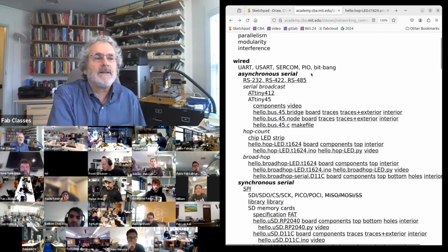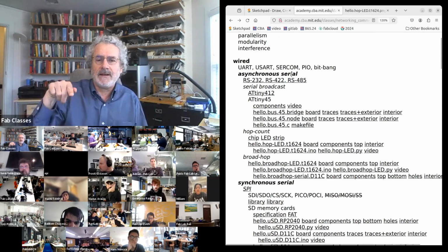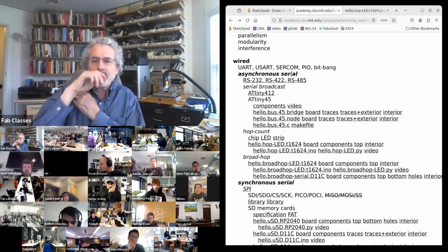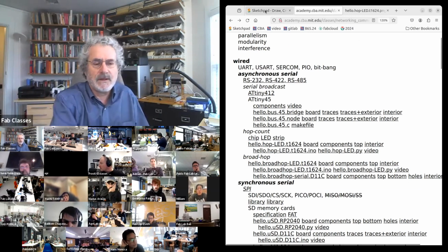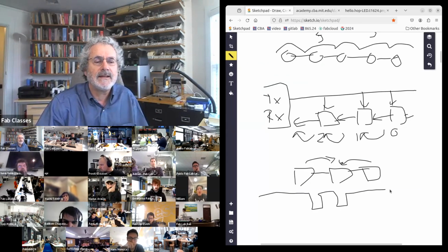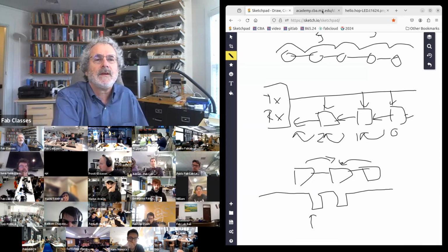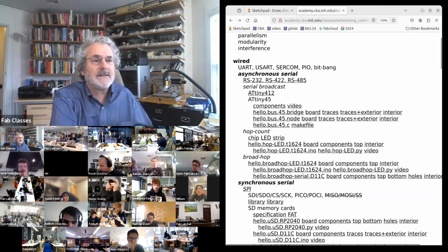Okay, so this is asynchronous serial. Serial means down the wire, I'm sending high and low levels. And asynchronous means the resting level is high, and at any time I can start sending data. It's up to the client to be listening and wait to see when that happens. So that's a serial bus.